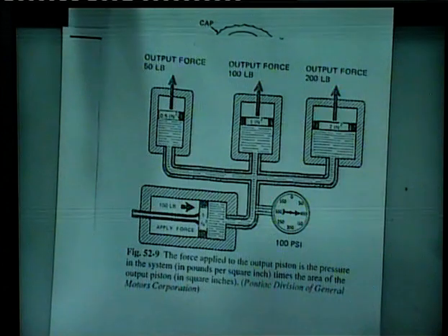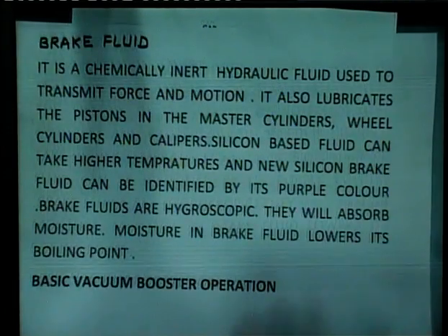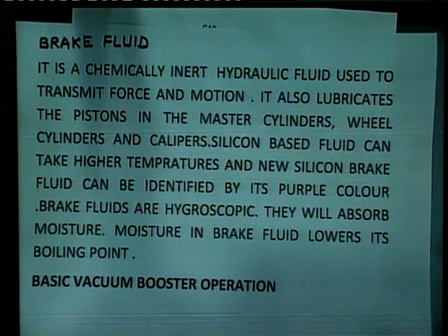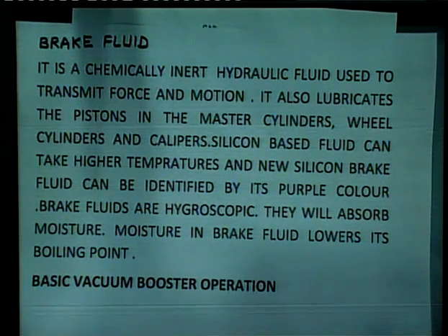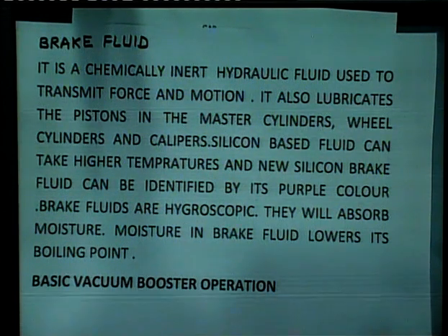And then let us see about the brake fluid. The brake fluid is a chemically inert hydraulic fluid used to transmit force and motion. It also lubricates the piston in the master cylinder, wheel cylinders and the calipers. Silicone based fluid can take higher temperatures, and new silicone brake fluid can be identified by its purple color. Brake fluids are hygroscopic, they will absorb moisture. So, moisture in brake fluids lowers the boiling point.